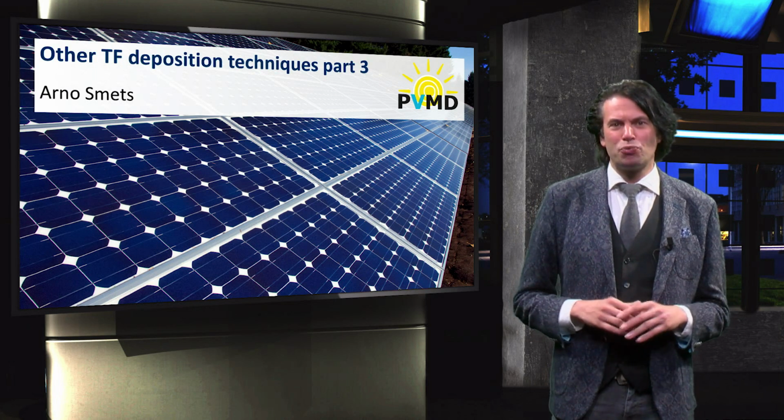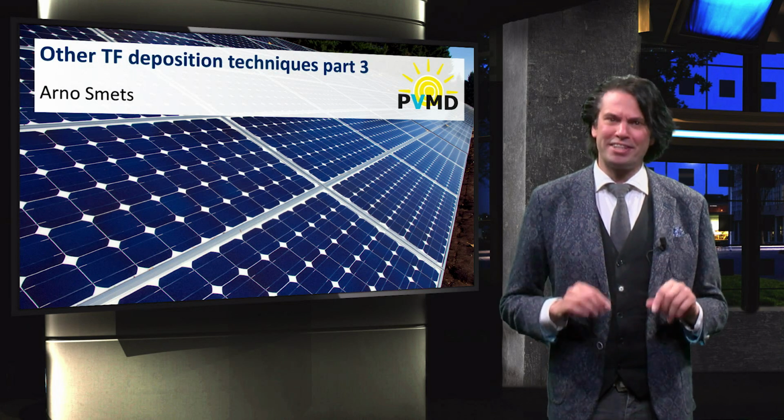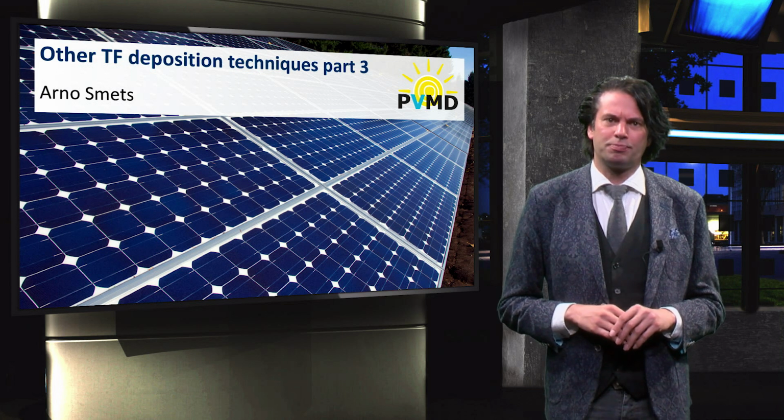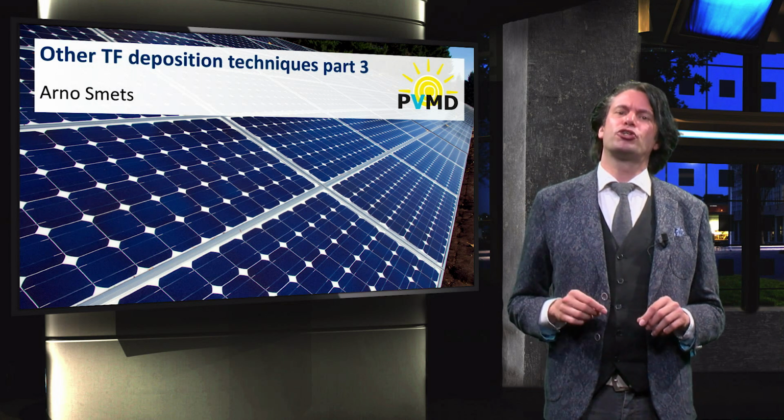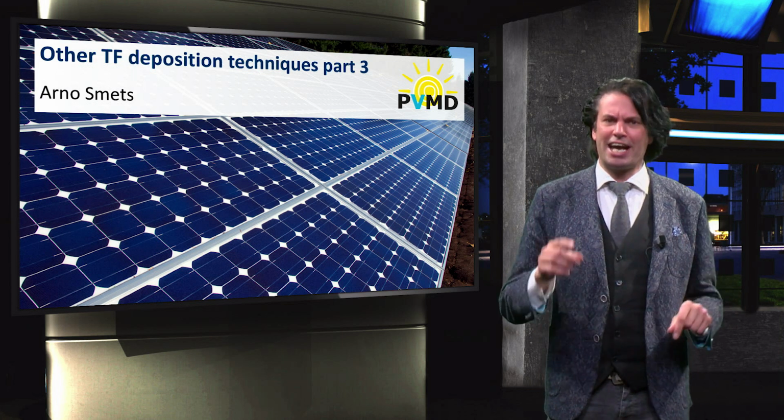In the previous videos, we discussed a number of important thin film processing techniques. We will now finish our discussion with atomic layer deposition and spin coating. In contrast to traditional chemical vapor deposition processes, ALD procedures consist of sequential alternating pulses of gaseous chemical precursors that react with the substrate. Each individual gas surface reaction step is called a half reaction.